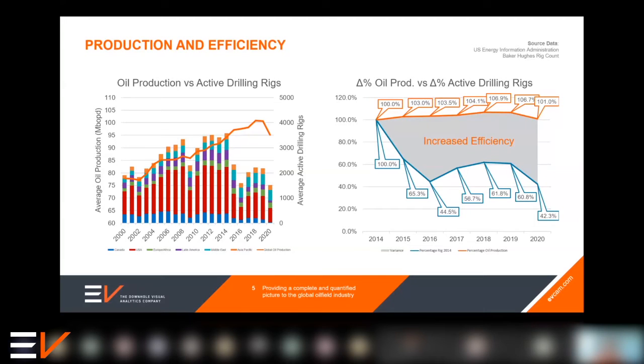And again, thinking about the unconventional wells in particular, frac hits are a major issue that's arguably compounded by some of these factors. The longer wells, their closer density together of the laterals, it means that there's much more interactions within wells. You're also putting more plug and perf assemblies in there and making more trips in and out of the well. So with all of these variables in play, when things go wrong at this early stage in well delivery, understanding the root cause plays a massive part in getting the operation back on track, and getting it back on track quickly. And it's here that we'll look at our first case study in addressing this problem in unconventional resources.